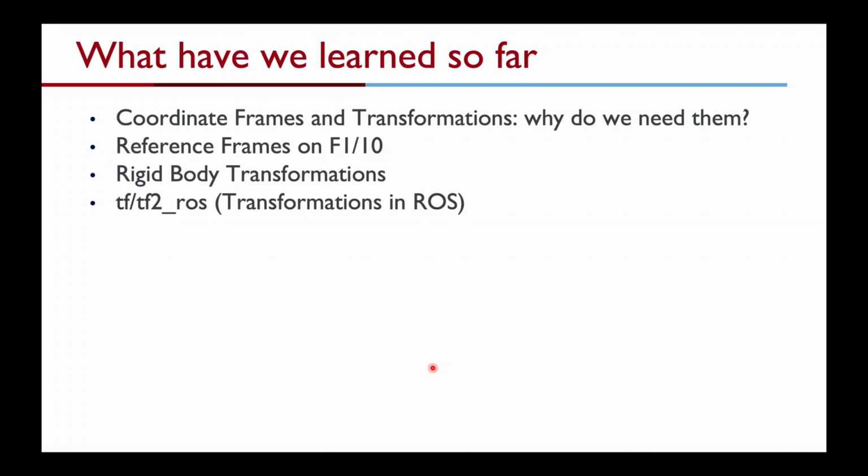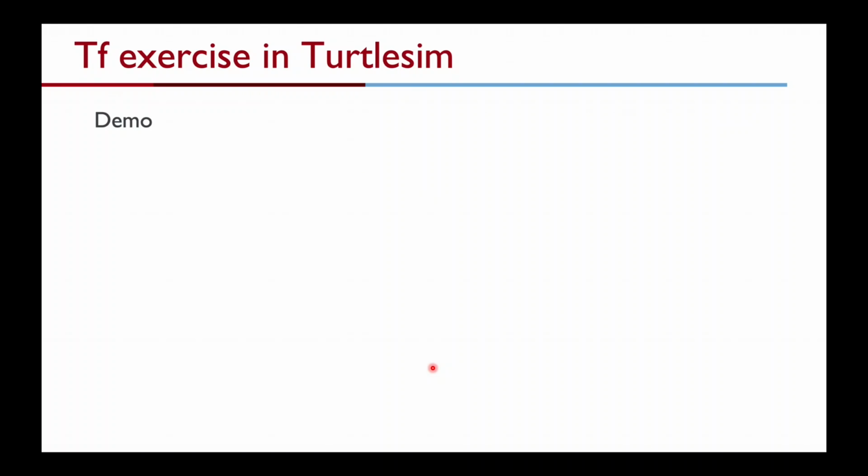And the take-home message is for you to be familiar with the TF tree, the tools that TF offers for us to debug these different transformations and understand how data is getting passed from one transform to the other. So with that, the lecture ends, but I will take a few minutes to show you some demos in TurtleSim. So let me quickly switch to that.